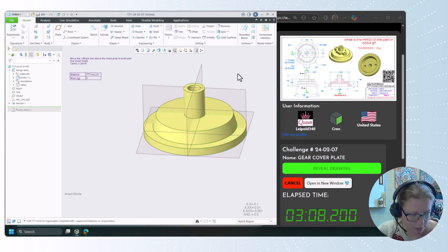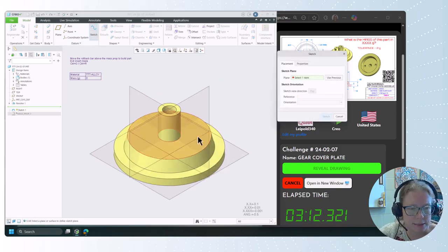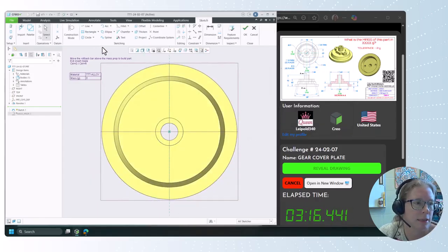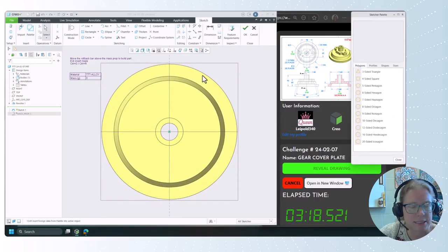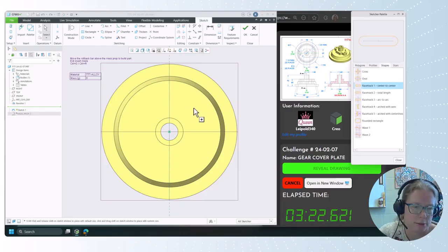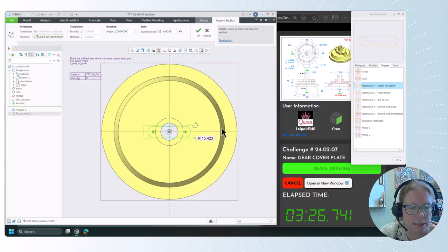All right, so there's our revolve geometry. For the top, I'm just going to make a sketch region. And we're going to start, it did mention the slot, so we can find that racetrack shape. So click and double click and then click to place it. If I drag it onto the center, I can use this little expander to make it bigger.